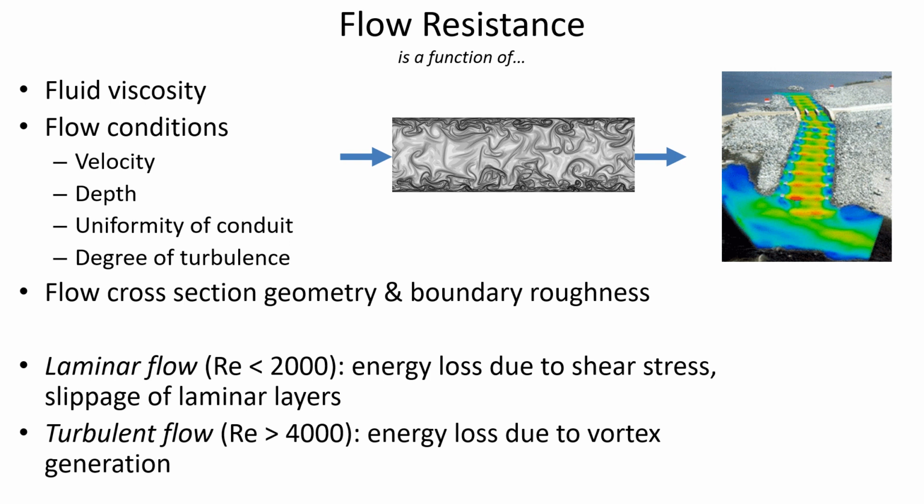And I'm sure that in fluid mechanics you learned about laminar conditions and how we assess whether conditions are laminar or turbulent by calculating, what does Re stand for? Anybody remember? Reynolds number, good. So below 2,000 and we'll have laminar, above 4,000 and we'll have turbulent, and in between, in the middle range, it kind of depends on what direction you're coming to the flow from.